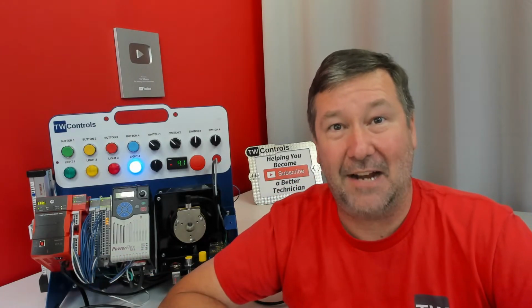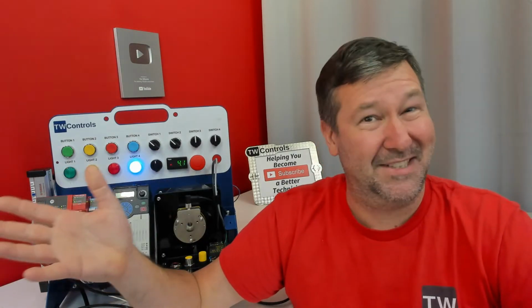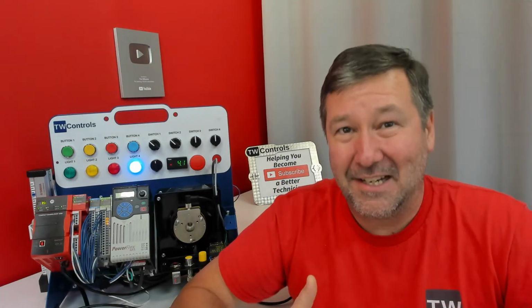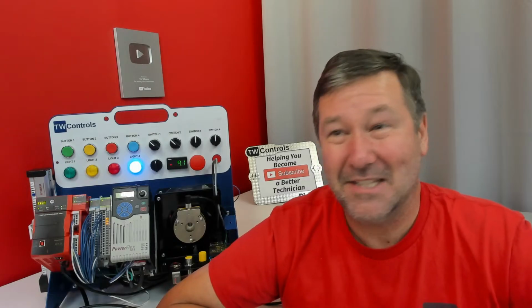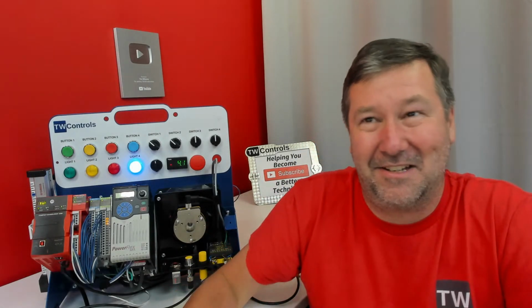It's in their instruction guide. Wait 2 minutes, and then you'll have a 169.254, and you should be able to find your PLC. Don't do that. You're not teaching them how to connect to the PLC once they graduate from your course. So we need to understand what our IP address is and then how to configure it.